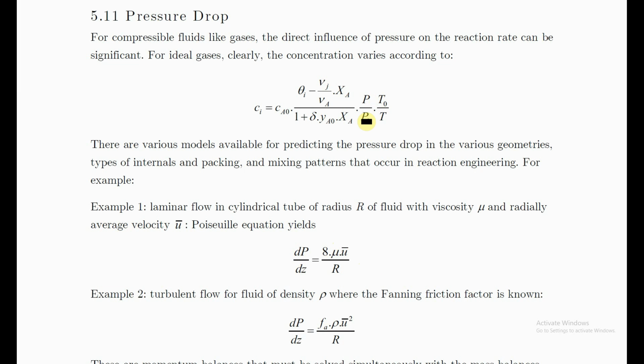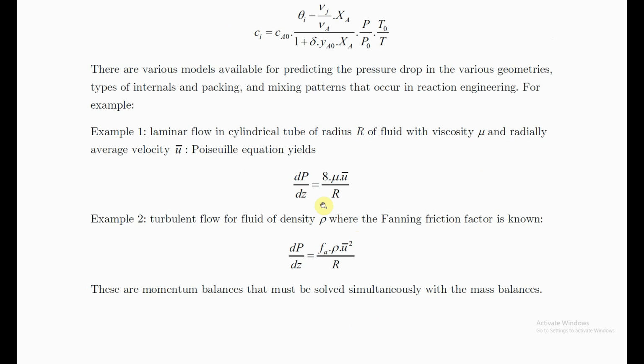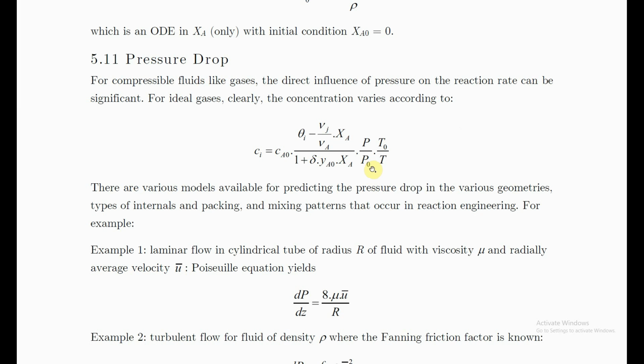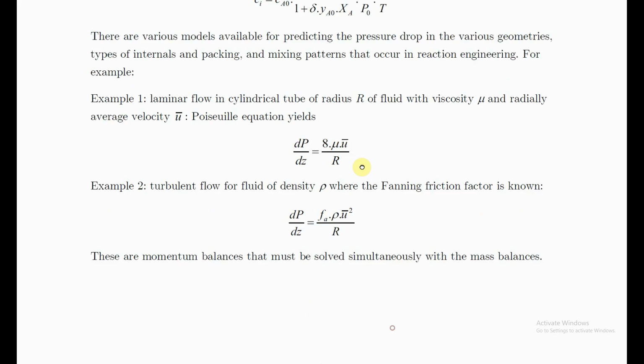So instead of trying to claim that the pressure is always going to be equal, if you just accept that the ratio of those two things will result in a pressure ratio like this, then you could estimate the pressure drop, and for that you use your standard fluid mechanics type considerations and relationships. And so you estimate the pressure drop, and compared with the inlet, you just update your pressure there, and then that helps you re-estimate your concentration.